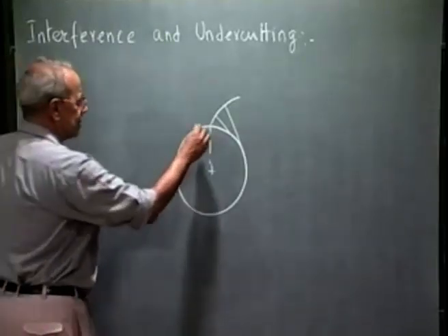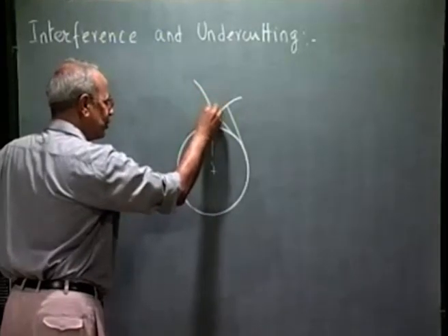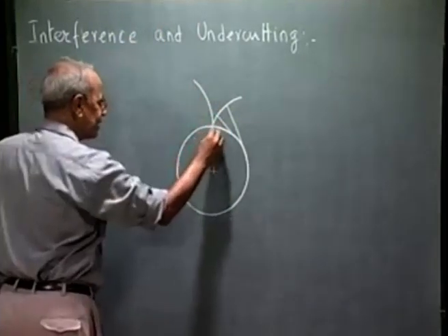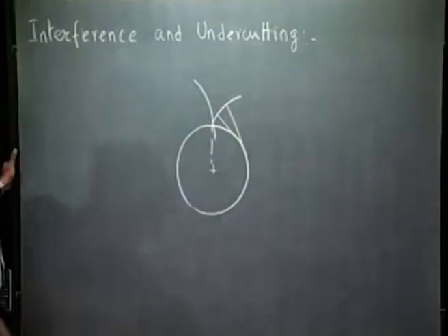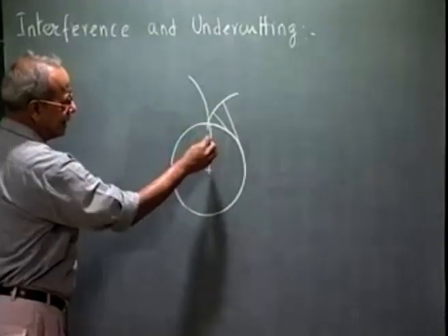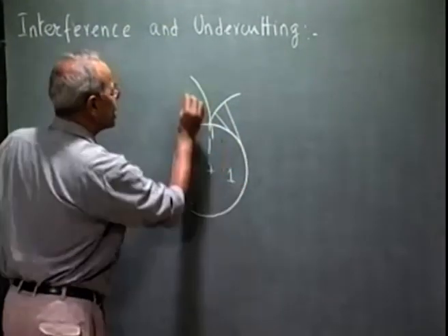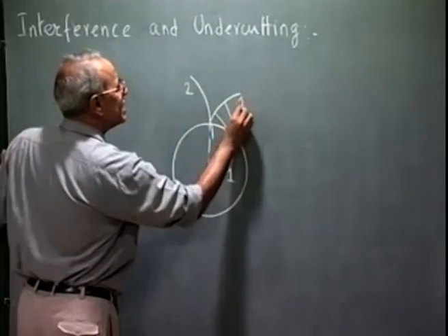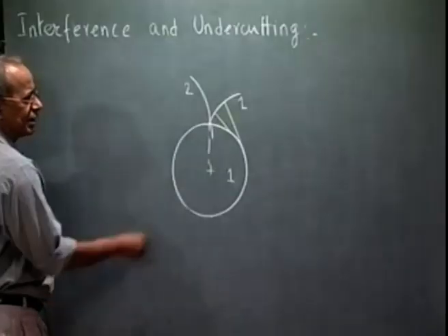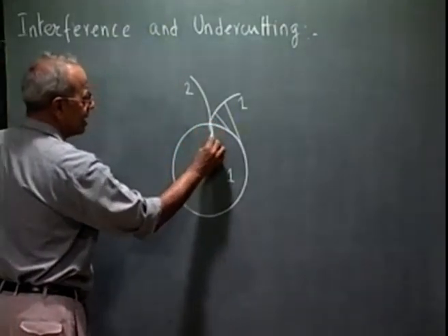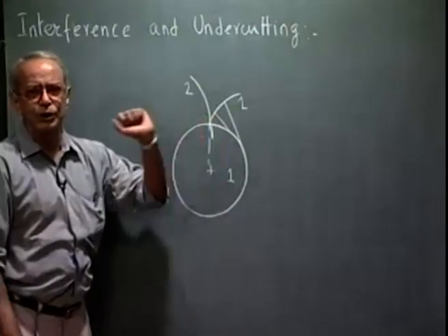If the mating profile, which is another involute from another base circle, gets inside the base circle, as we see, there is no involute of this gear, say this is gear number 1 and this is 2. Gear number 1 does not have any involute inside this base circle, whereas the involute of the other mating gear is getting into the base circle.